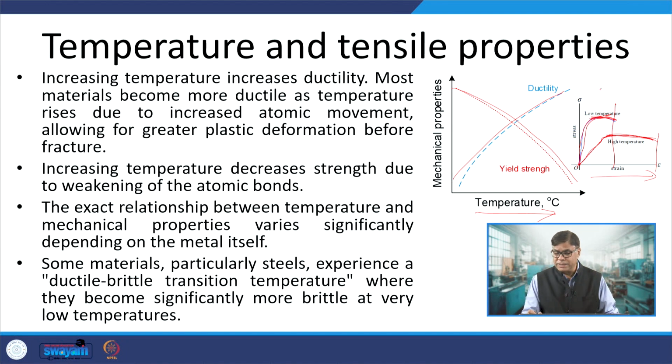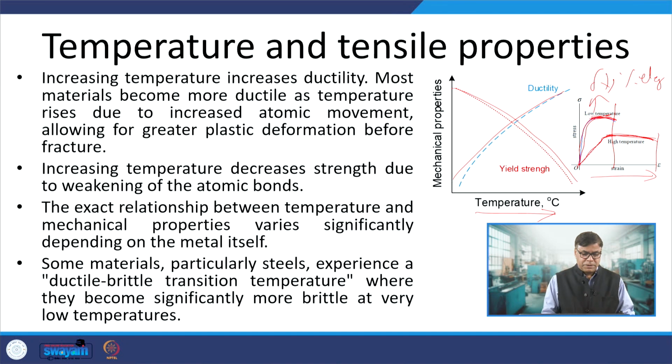So, this indicates that material strength comes down, and percentage elongation, that is the strain, which is also known as ductility, increases with the increase of the temperature. While strength may be high at low temperature, elongation will be less at the low temperature. So, increasing temperature increases the ductility.